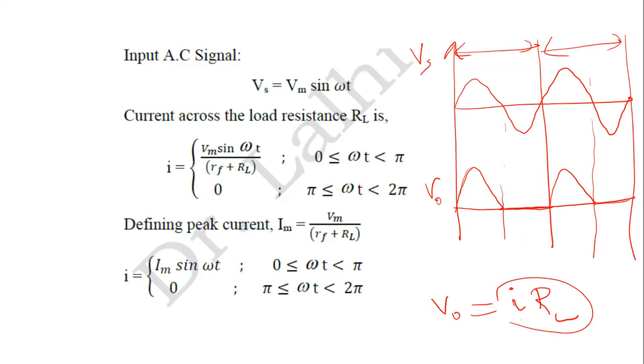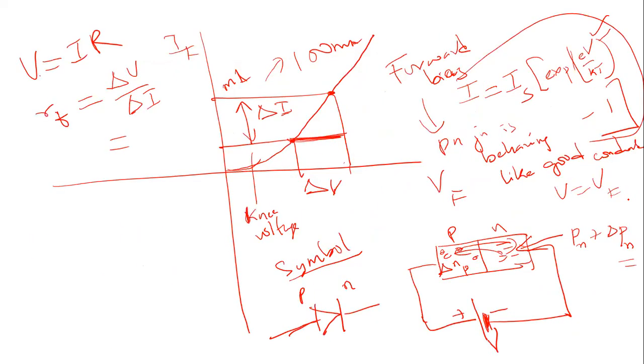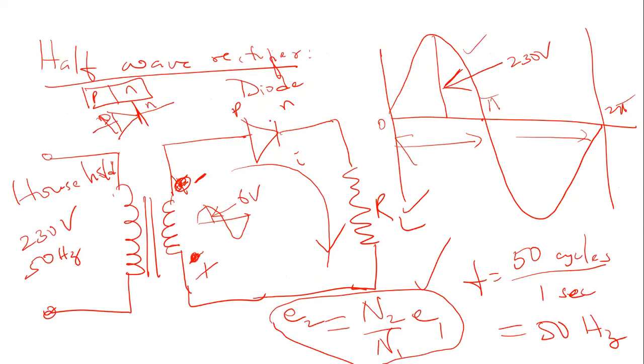Okay. So in this circuit, as you see, by the introduction of this diode, it allows the current to pass through the load resistance only in one direction, that is from top to bottom. Current flowing from bottom to top, that is the anti-clockwise direction, is now suppressed. So when you are connecting the voltage in a reverse cycle like this, the diode is reverse biased.